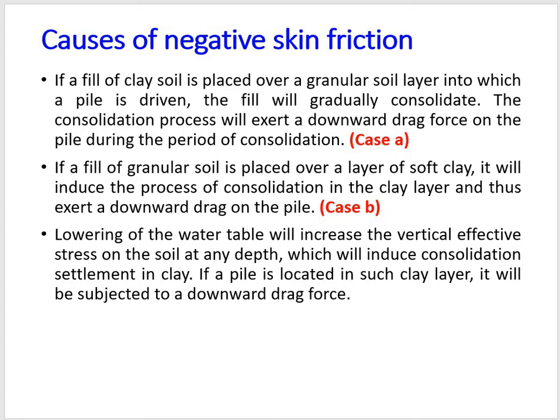And obviously in situations where the water table is considerably lowering, what happens is that the effective stress will increase. The vertical effective stress on soil will increase. That will also induce consolidation settlement in clayey soils, and as a result of this there will be a downward drag force.